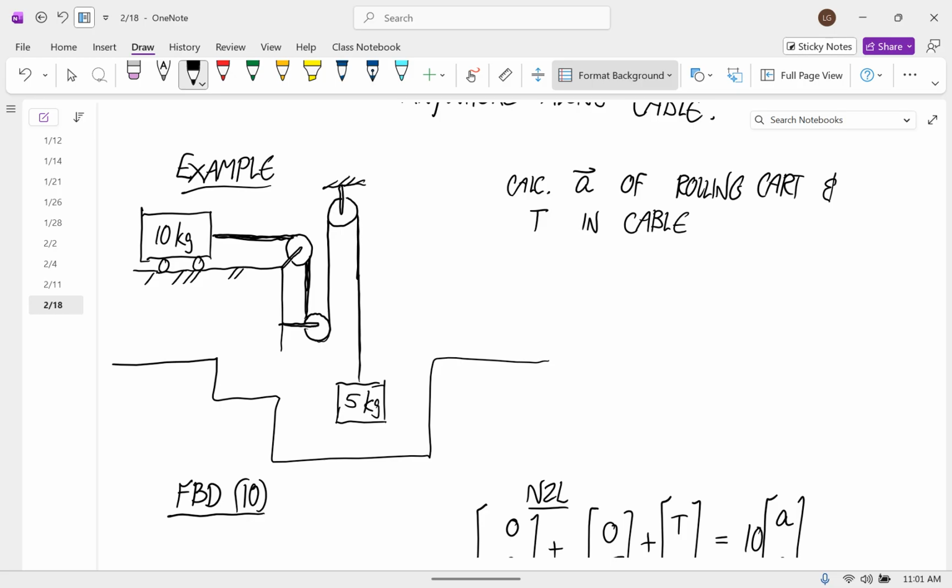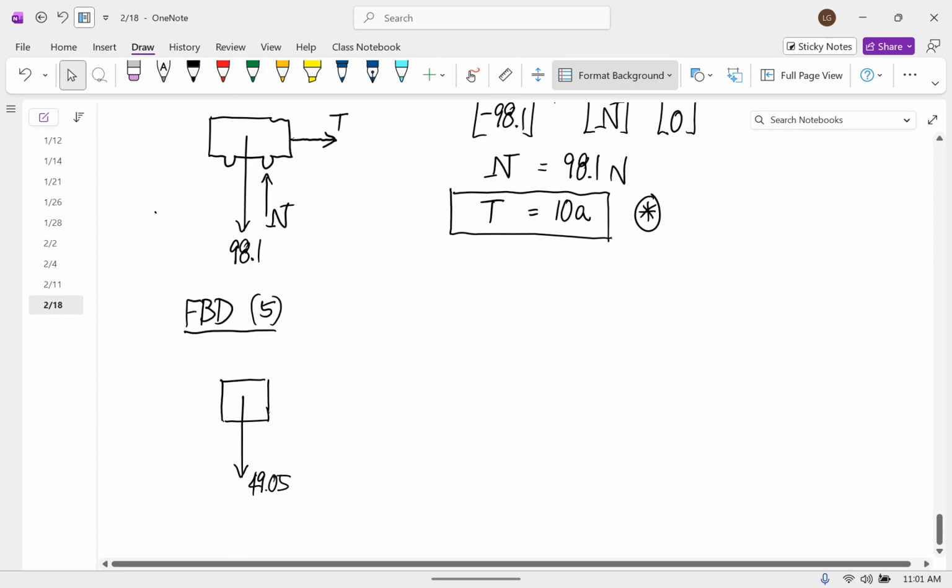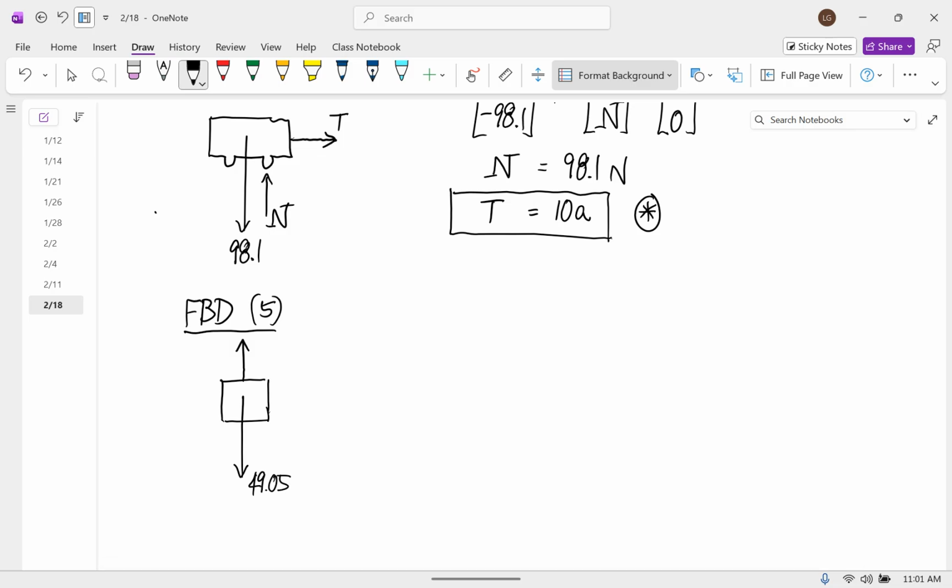What about the magnitude? Well, since all this cable does is cross through ideal pulleys, we know that it has the same magnitude T as the force on the other body. So this force is parallel to the cable, away from the body, and we know it has that same magnitude T. No other contact with the surroundings.